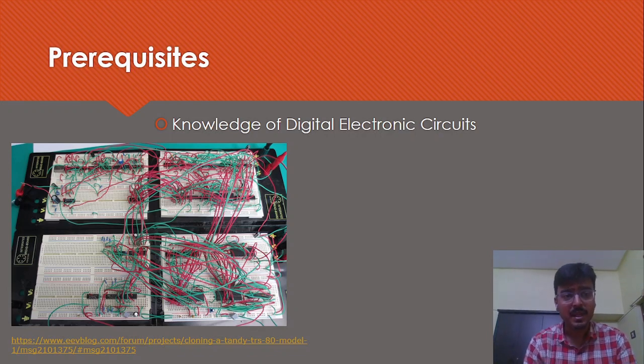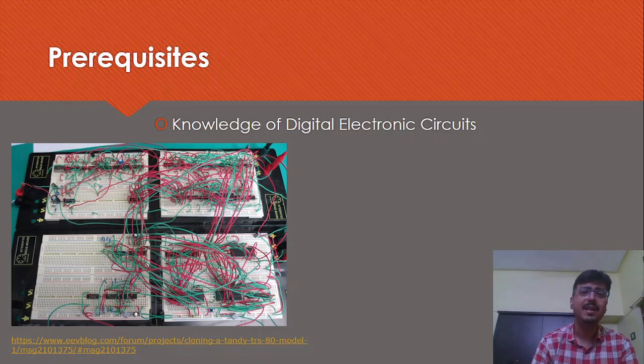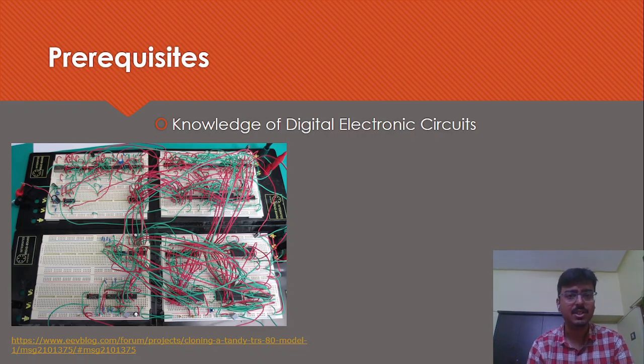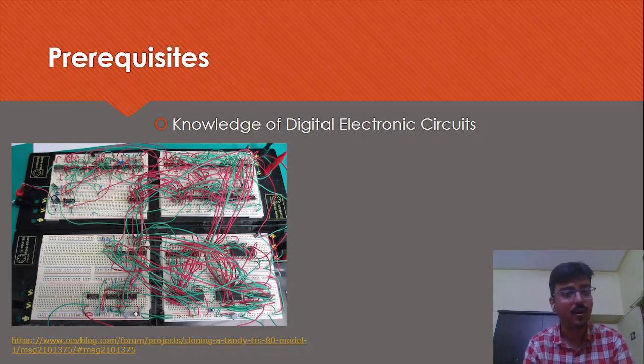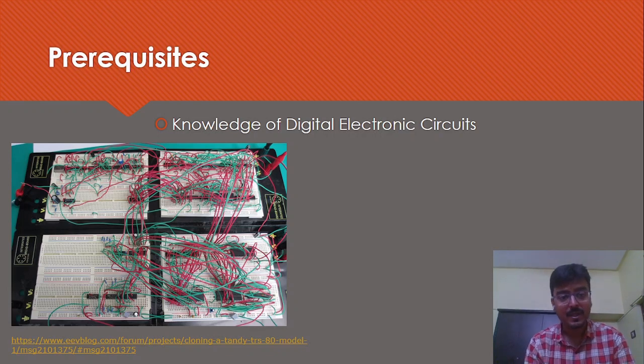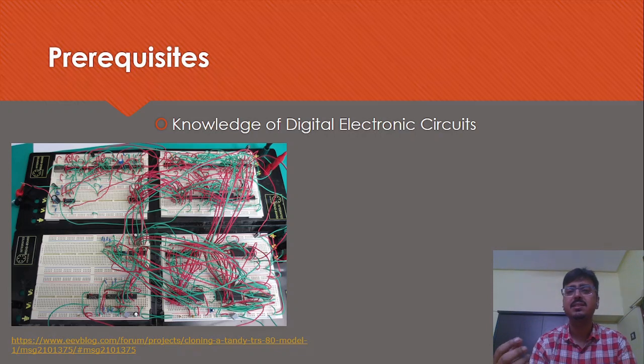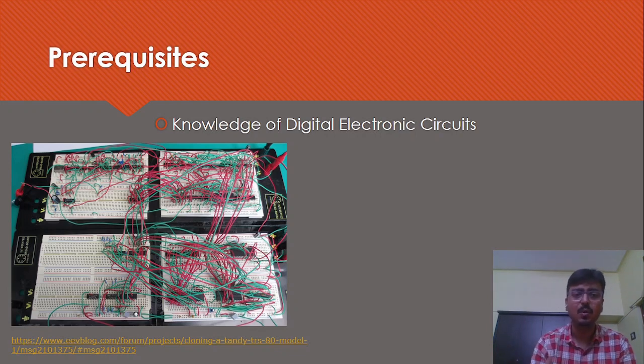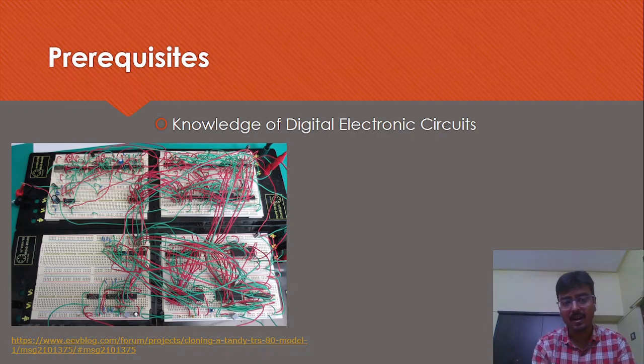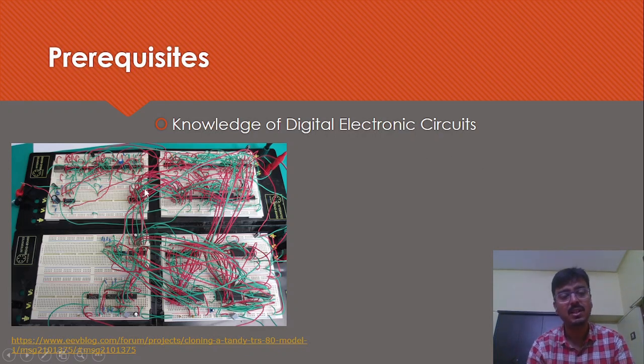So you have seen these ICs that you have used, and most of them are 74LS series ICs, which are TTL logic ICs, transistor logic ICs, and most of them have fewer than 12 gates. Many of them have only 4 or 6 logic gates on them. As a result, to design fairly complex digital circuits using those ICs, the circuit becomes this clumsy.